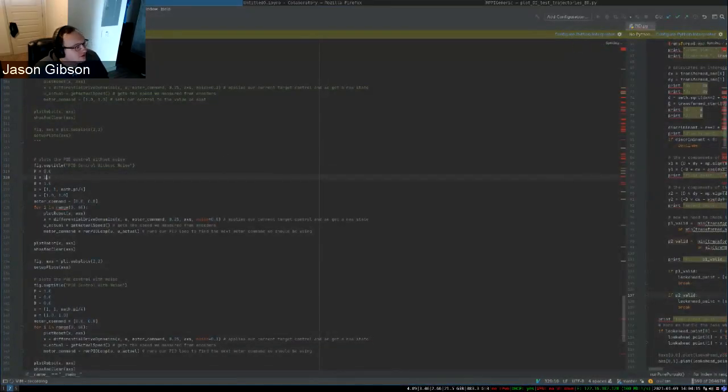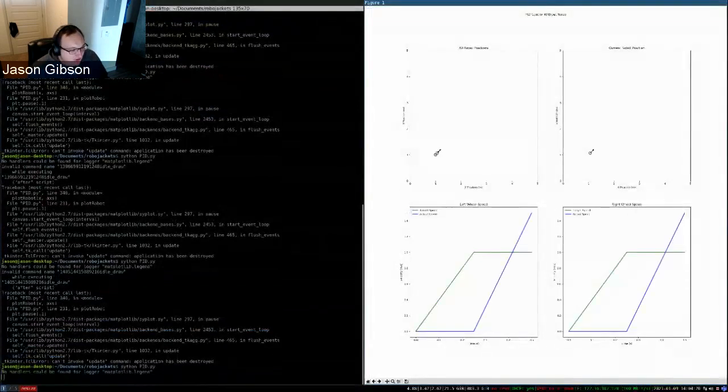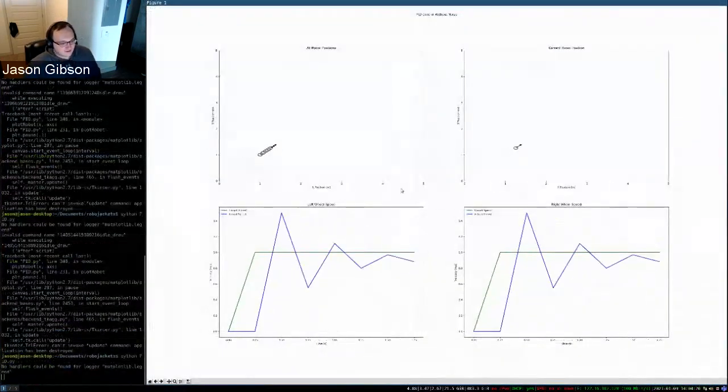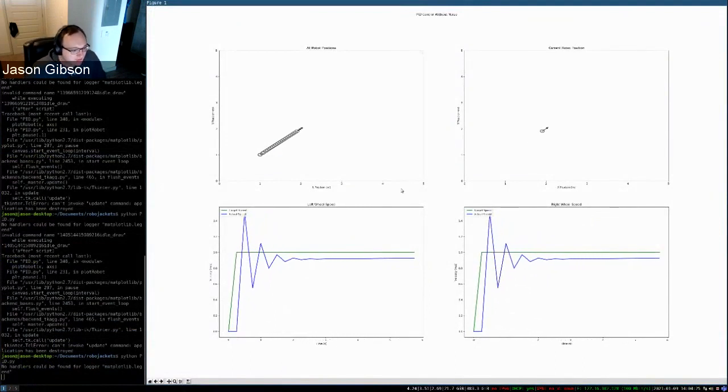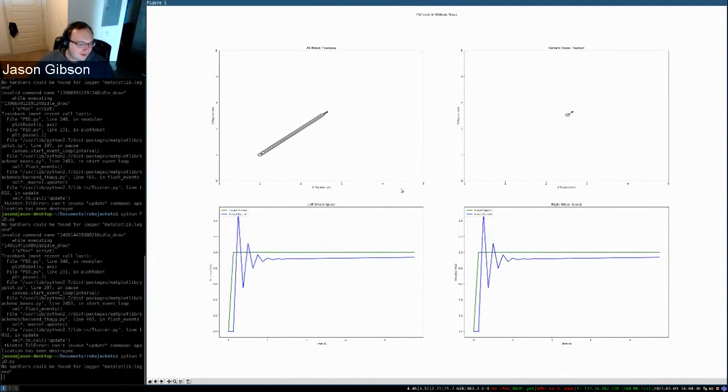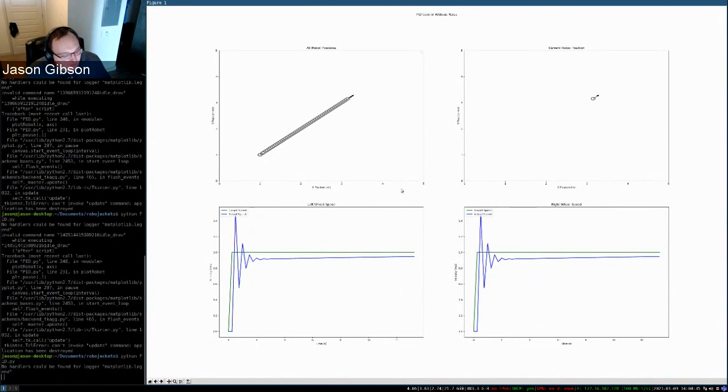So now we're going to increase I. We're going to increase our I value, and we're going to see the difference. This is even with that higher P, and see it's not a problem at all because you settle closer. It's probably hard to tell on your screen, but what you'd actually see is that the blue line is getting closer to the green line over time. As that accumulated error builds up, it is increasing the control value, but obviously not as much as we would want.